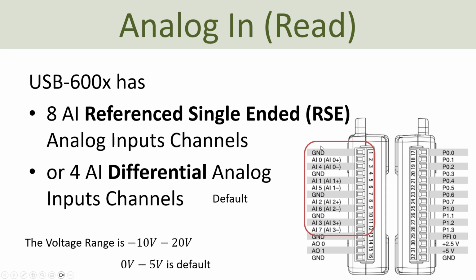Here on the left side you have the analog input pins, and for these DAQ devices you typically have 8 analog input, so-called RSE channels, or you have 4 differential channels. So for the reference single-ended channels you have 8: analog input 0, 1, 2, 3, 4, 5, 6 and 7. So 8 RSE channels, but if you use the differential channels, then you have only 4.